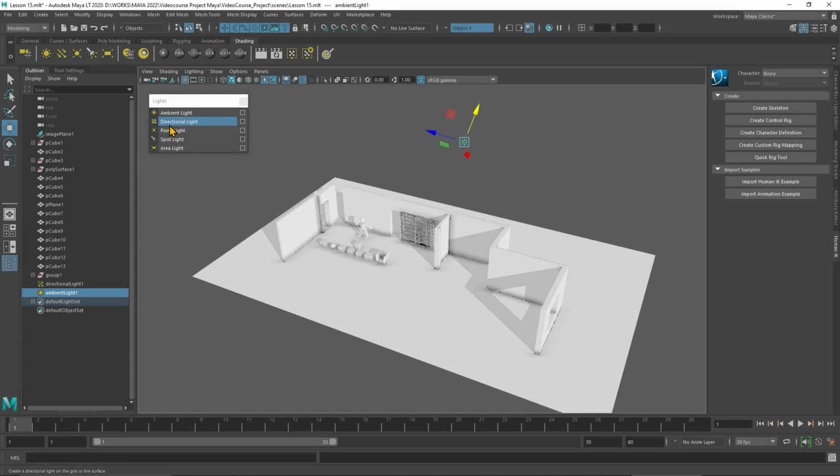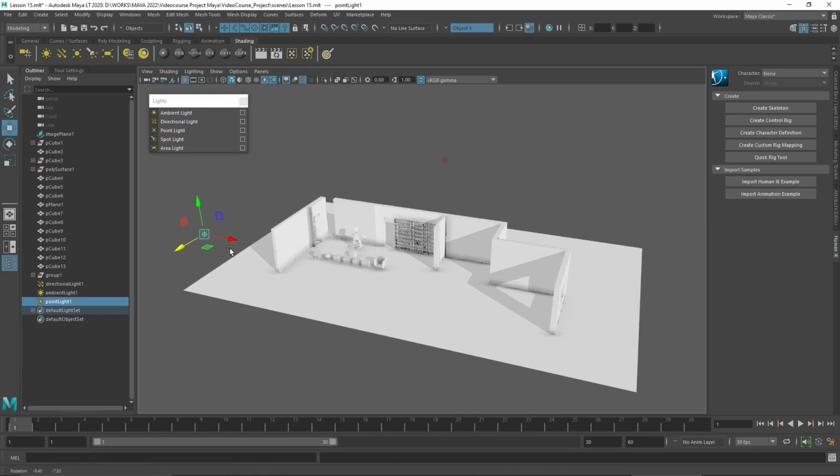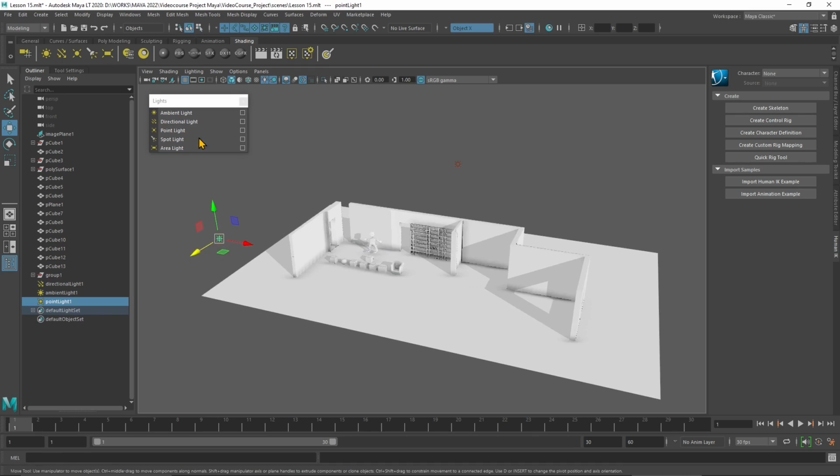Now you can use both the ambient light as a skylight and the directional as a sunlight. So if you want to set up an exterior rendering, you can use ambient and directional. These two can be used as natural lights for exteriors and for interiors. If you are in an interior, you can make the sun get inside the scene and then use that as a natural light for interiors. Now I'm just going to anticipate that in Maya Light version, you don't have an advanced rendering system, so you need to switch later to another one, and I will talk about that later.